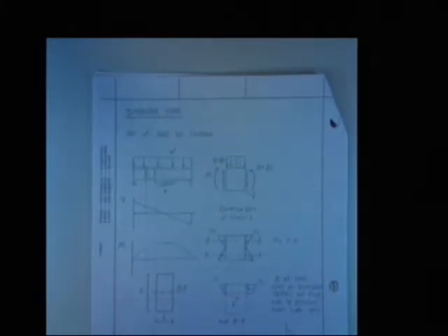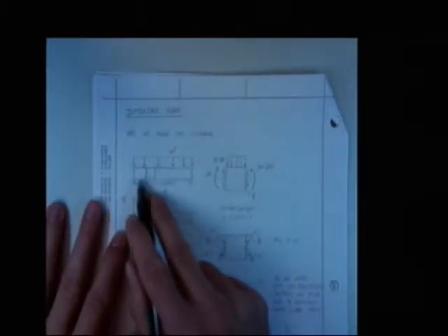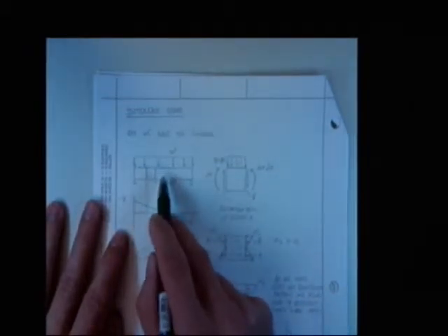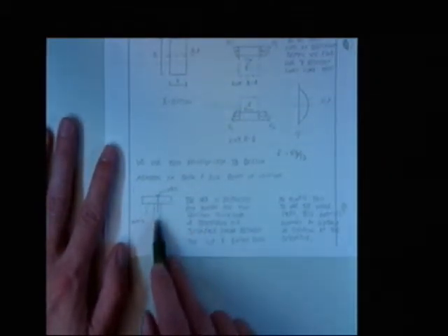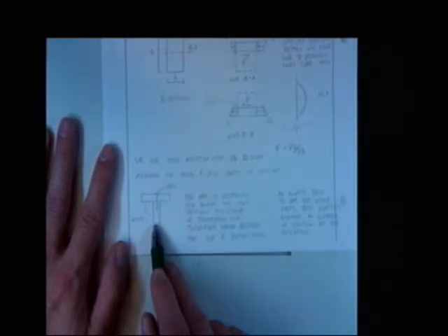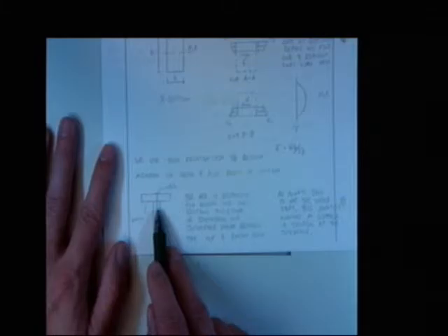We're going to start to talk about what happens when you design composite girders. Composite girders mean when you have a beam, and then on top of that beam you put something else, like a concrete slab on top of a steel girder. You've seen this, believe it or not, when you did strength of materials, because you talked about nailing 2 different pieces of wood together, and how big are the nails and how close do they have to be. So you've worked these problems. It's just too bad they lied to you in that class.